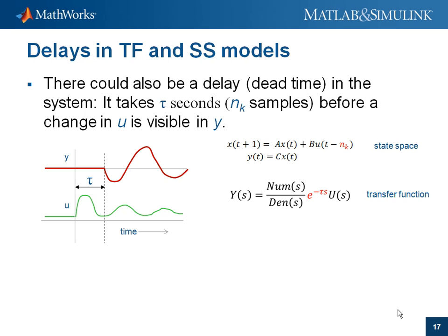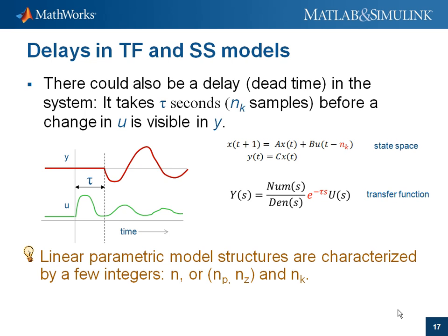There is one more feature that is essential for models. Often there is a delay or dead time in the system. That is, a time interval passes before the input affects the output. In our hairdryer system, for example, it will take some time before the power change in the heating part affects the outlet temperature, simply because it takes some time before the air has been transported to the outlet. It is important to get an idea of this delay time. It could be estimated or measured from data, and it will be part of a model.